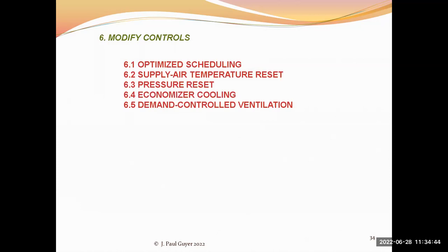If it's too high, then you're probably doing something like using dampers to reduce the static pressure downstream, and that higher pressure takes more energy, of course, than if you have the pressure set where it is needed.